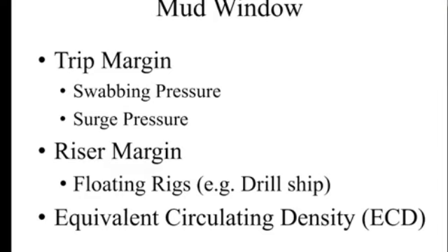Why? Because the pressure at the bottom of the well will be equal to the hydrostatic pressure plus the pressure drop due to friction inside the annulus or the annular section. And we know that the pressure drop due to friction is more than zero. So bottom pressure will be more than hydrostatic pressure.